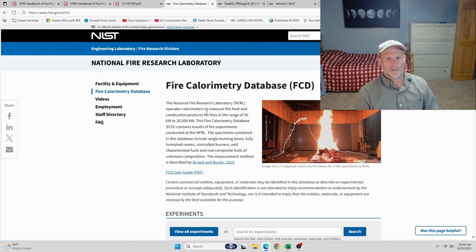It's really a steady state value. But if you just measure your oxygen output from a fire and know what the input oxygen concentrations are, then you can calculate overall heat release. And that's how that system works.